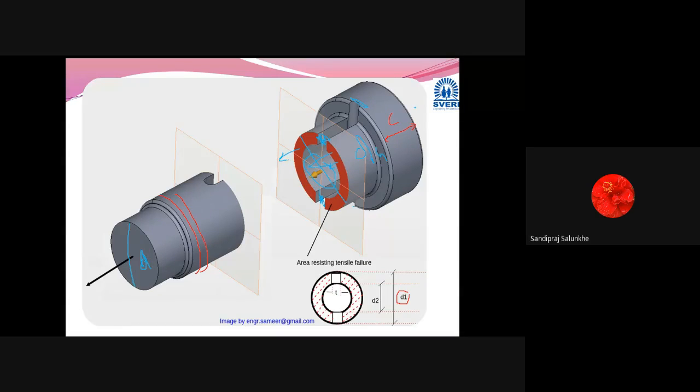Then definitely this solid area will be able to sustain that tensile stress. So we don't have to bother about it. We just see what the external diameter or collar diameter will be. Then why have we provided this collar? Because when we insert this pivot, the pin which we insert here has to be restricted in its motion. So we have considered this collar.